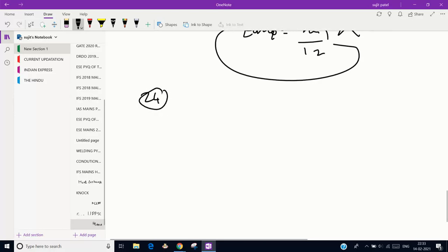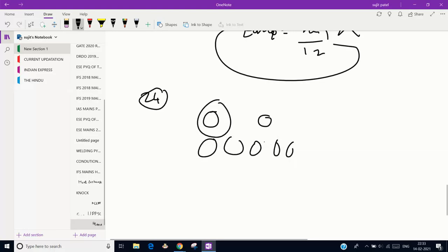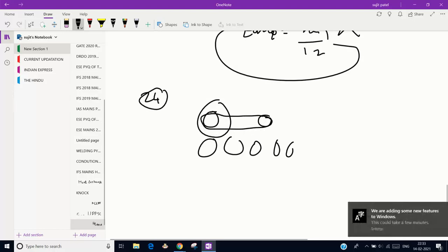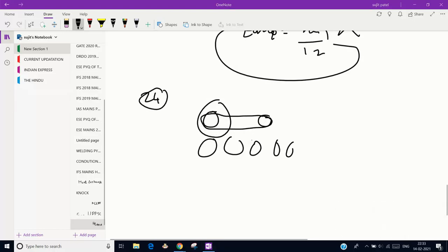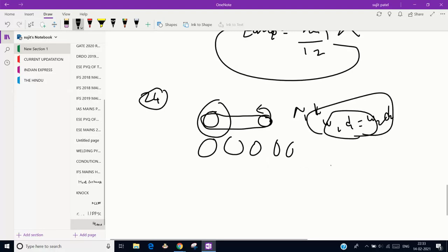Next is one question on a belt and pulley drive, with one belt, two pulleys, and gears that are connected. You might be confused whether it is a belt drive or whether you have to solve with the length of belt of contact. But it is just omega 1 into d1 is equal to omega 2 into d2. That is the no power loss condition that you have to apply. I think the answer is clockwise and 255 rpm, I think 255.65 rpm.